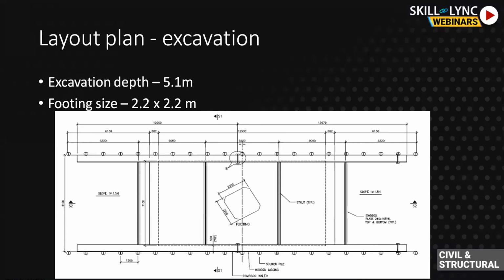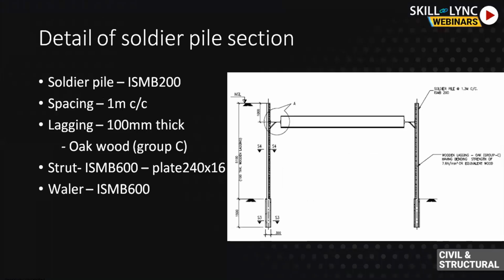Here the arrangement is not box type. We have slopes on both sides so that there is access to the bottom of the excavation. After the design, which is carried out using PLAXIS, we need to design the soldier pile wall for the required forces, and the strut and waler are designed for the required forces.